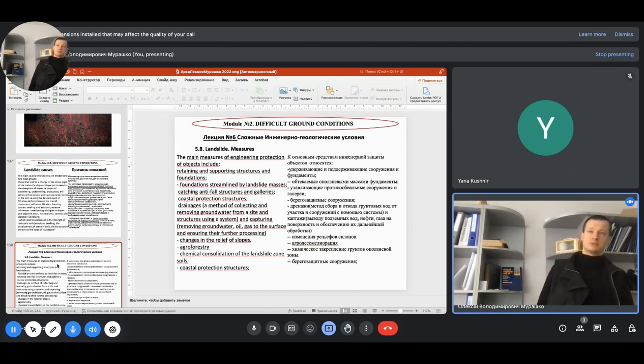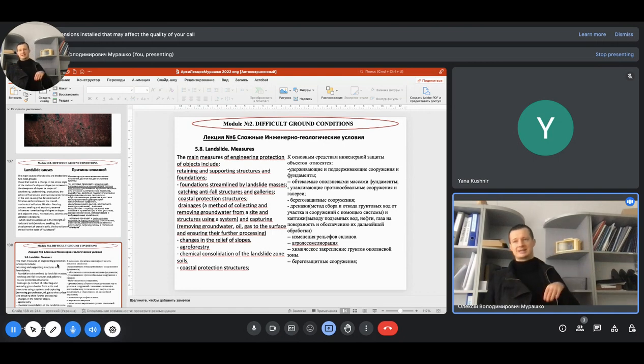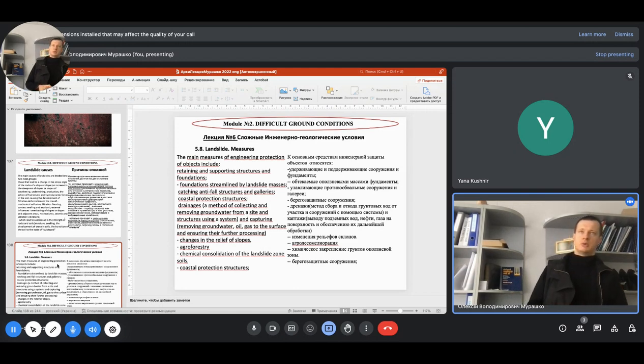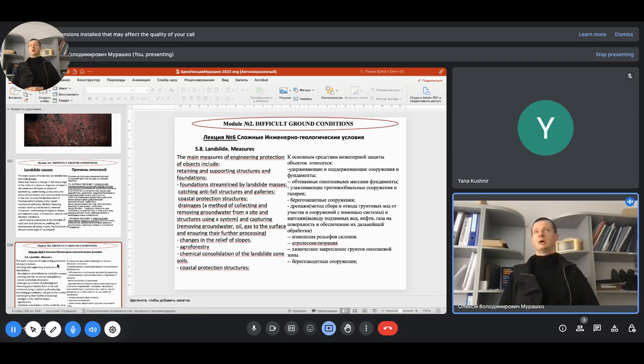Roots of trees dig deeply underground and grab the solid ground, and can work as a good connector of the not strong enough surface part of the landslide with a strong underground part. This connection can be obtained by the use of tree roots and other plants.